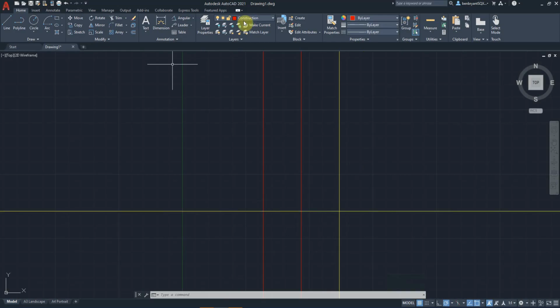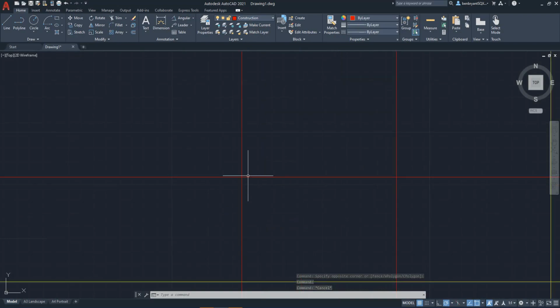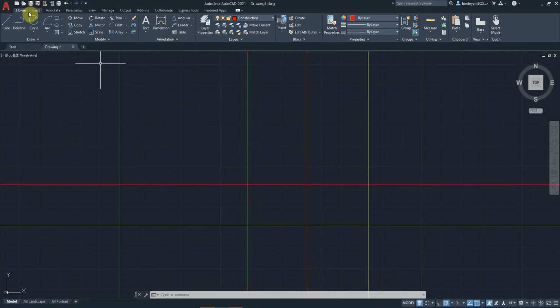So what I now need to do is an offset. I know that my arc is 20, so it's got a radius of 20, so I'm going to lift that up 20, and then I'm going to color this one back to red, just so I don't get confused with my base. This intersection point here is now the overlap for my radius arc. So using the radius tool for the circle, I choose my center point, put R20 in, and there's the first line of my arc.